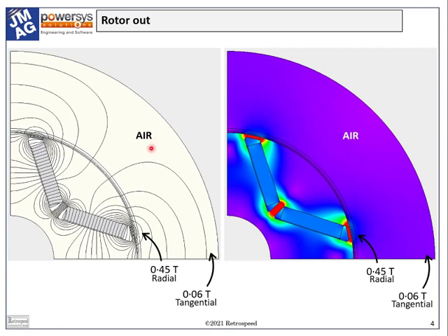The reason for this is to underline the fact that these rotors require very careful handling in the factory. Even out in the open, the field is strong enough to attract ferromagnetic objects. Field gradients are very high, not only in the radial direction but also around the rotor.